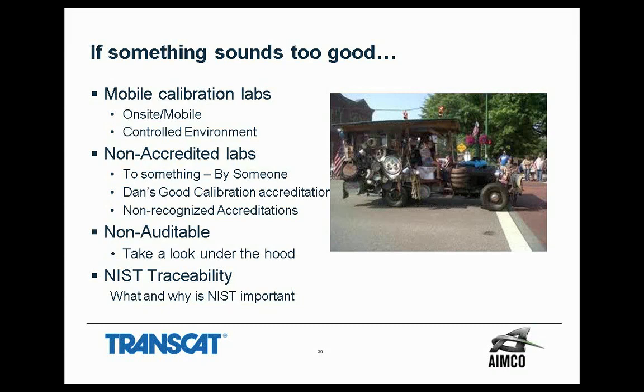But Dan's Good Calibration Company can pick that screwdriver up, drive out to your site, and calibrate your torque wrench. That doesn't mean that the torque wrench is traceable. It just means that screwdriver was produced in this traceable environment. The screwdriver itself doesn't measure. There's nothing on there to adjust. So by definition, it's not traceable. So you just got to be careful with mistraceability. You're seeing it a lot more in the marketplace, especially when people buy new instruments. So something to look out for.